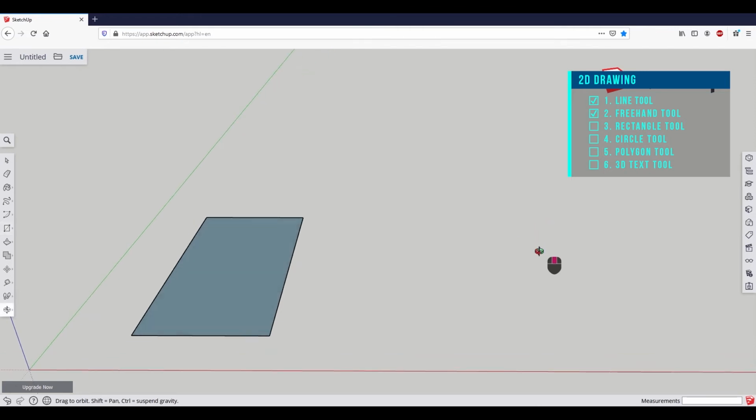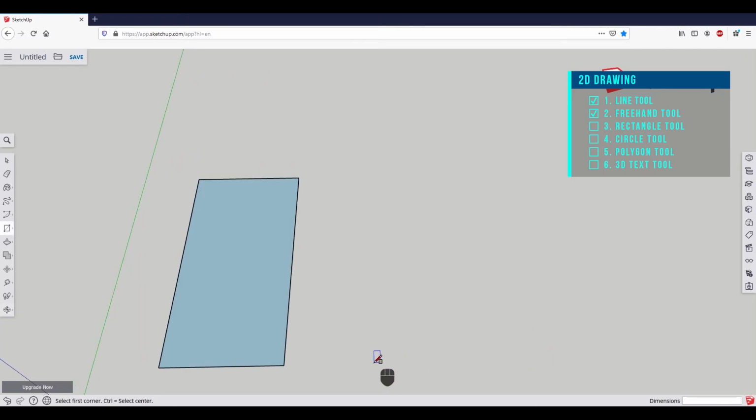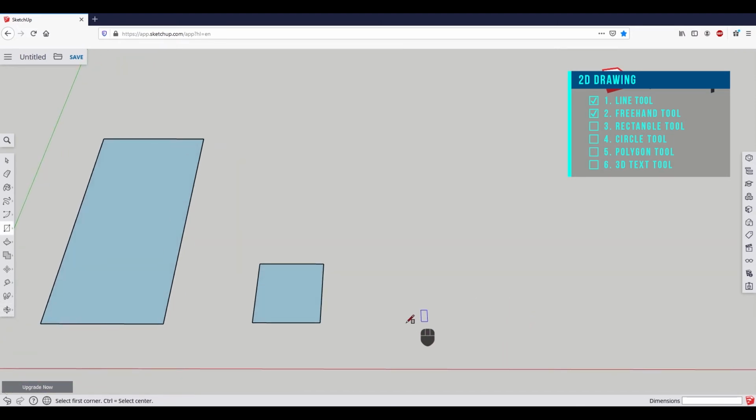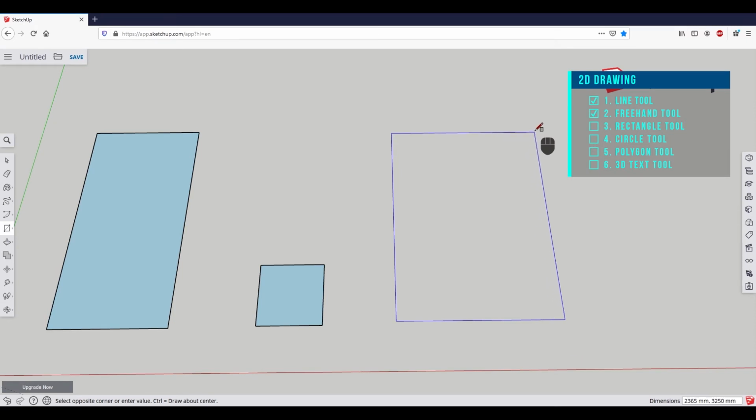If we orbit the view from top to bottom and draw a second rectangle next to it, we can now slowly move the mouse, and you can see that a dotted line will appear. With the help of this dotted line, we can draw a square or, alternatively, a rectangle in golden section. For this purpose, we draw another rectangle next to it, then slowly move the mouse and wait for the pop-up golden section. Now confirm the shape with a second left click.